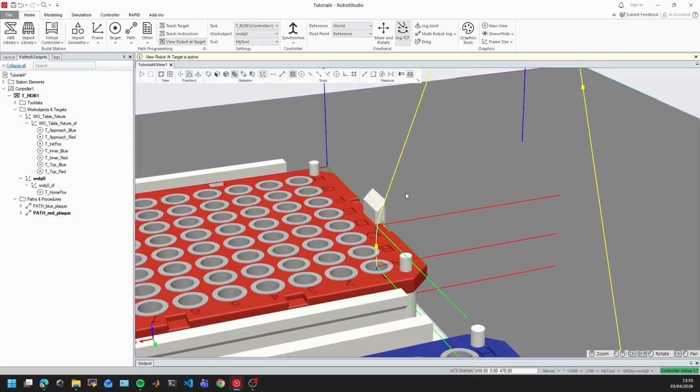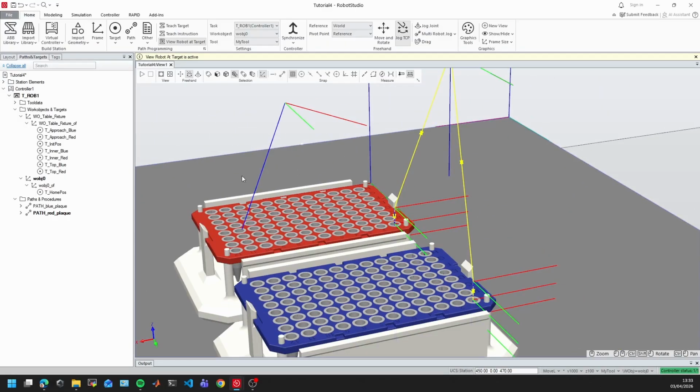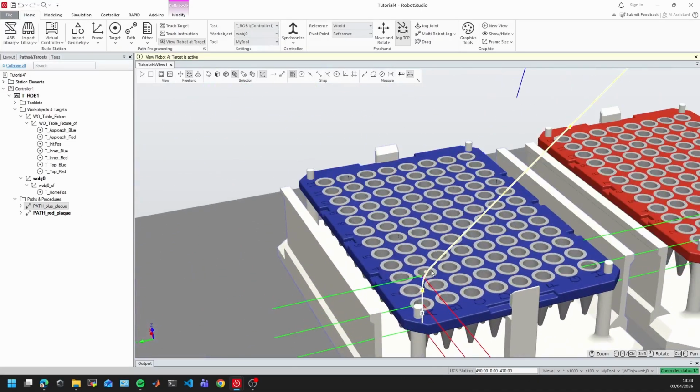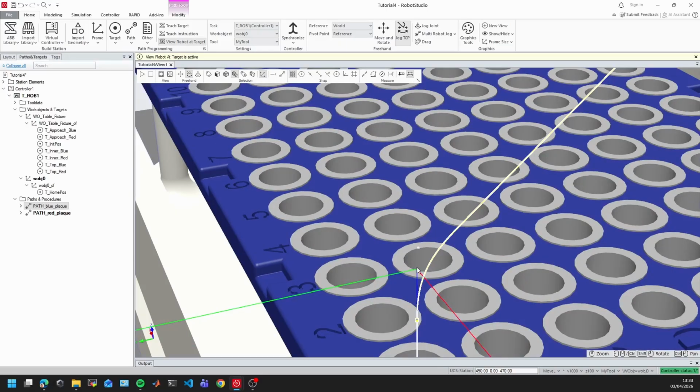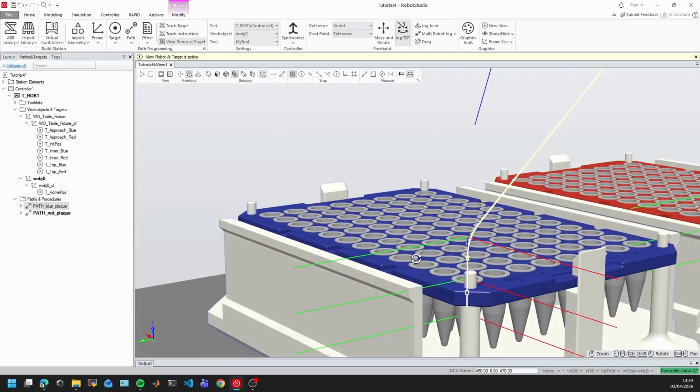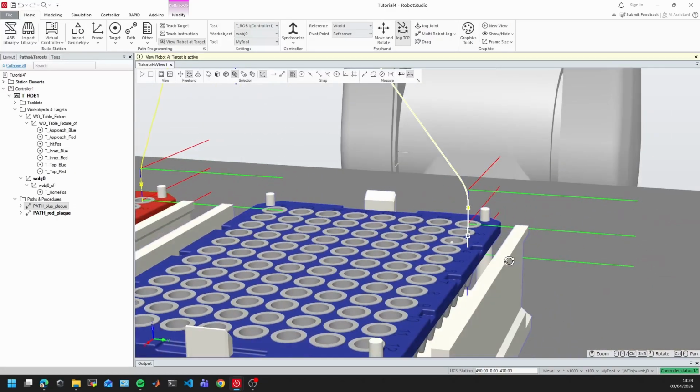So basically, when I'm making the path, I'm telling my path generator, okay, you have a tolerance of 100 millimeters. It doesn't matter if you don't touch the point, as long as you are not 100 millimeters away from that point. So now I'm giving the path generator more flexibility.